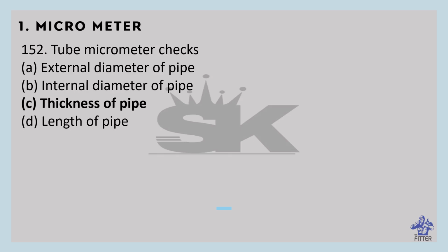Tube micrometers have a cylindrical anvil positioned perpendicularly to a spindle and are used to measure the thickness of tubes. Micrometer stops are micrometer heads that are mounted on the table of a manual milling machine, bedways of a lathe, or other machine tool in place of simple stops.